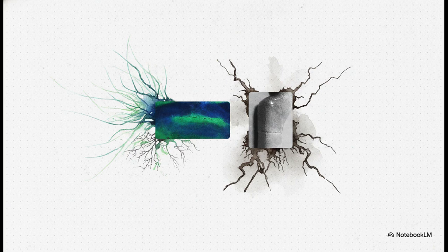Sometimes they sit right on the surface, which you can see clearly in a standard visible inspection. But a lot of times, they hide just beneath the surface. To catch those hidden ones, inspectors use subsurface techniques, like fluorescent liquid penetrant testing. Check out that vibrant green glow. That liquid actually seeps into the microscopic cracks and lights up under special lighting. It literally makes the invisible visible.